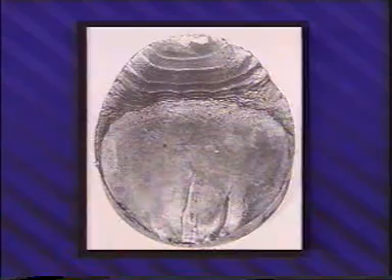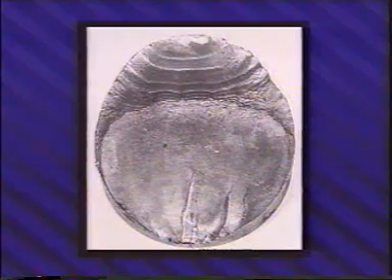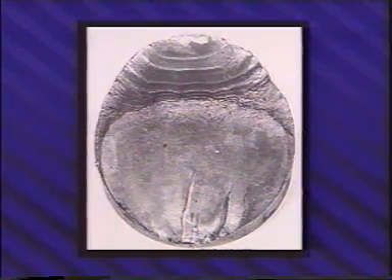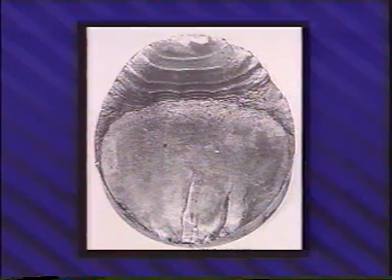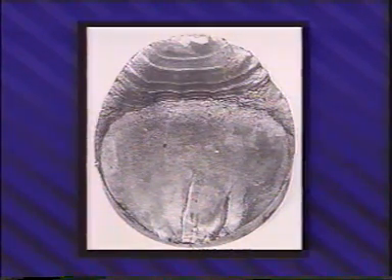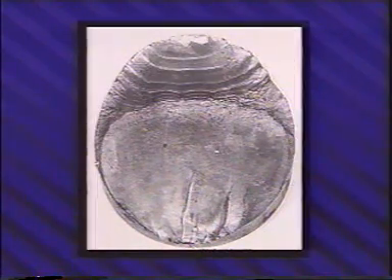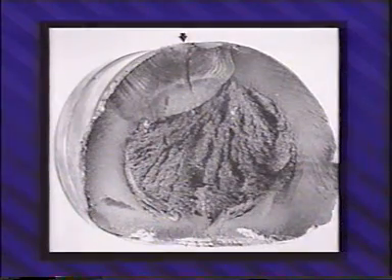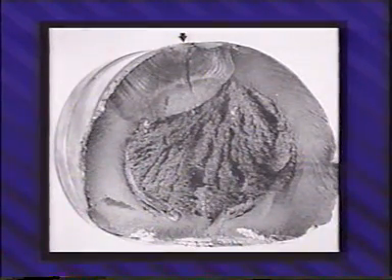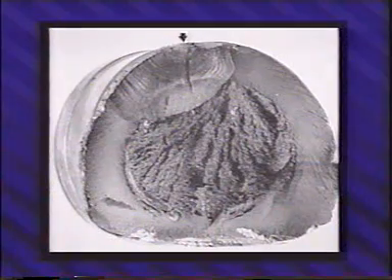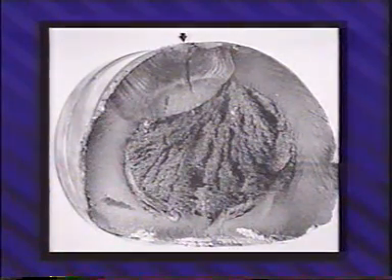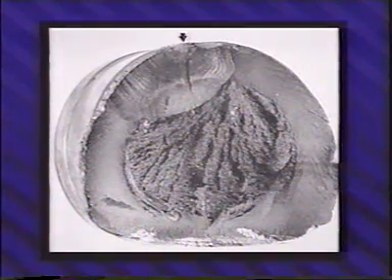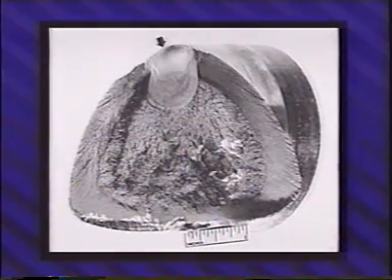On the macroscopic scale, early crack extension occurs under conditions that give a typical smooth-textured, grained, flat-faced surface to the fracture. When produced under random repetitive loading or sequences of high and low stress amplitudes, the characteristic beach marks frequently result. It is possible for a fatigue crack to originate in the hard, strong region of a part and propagate into softer, weaker regions. This is usually due to heat treatment, imparting intentional variations to the properties of the material. Several different types of fractures may exist.